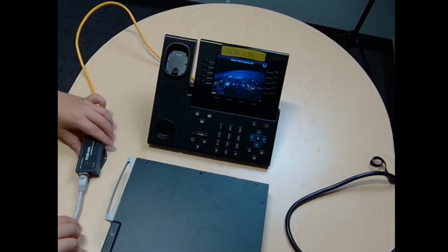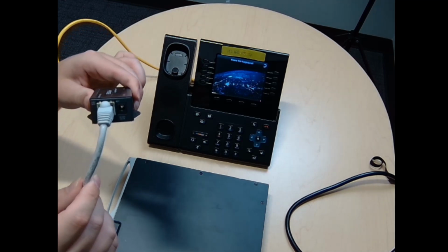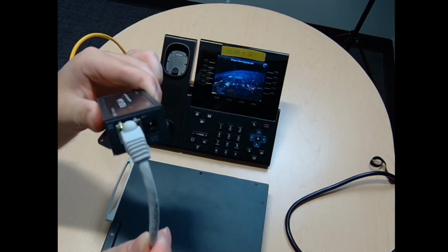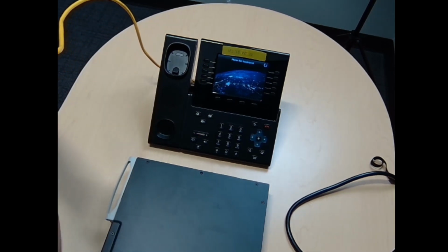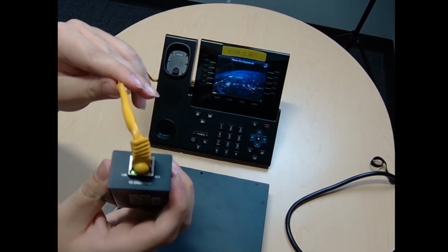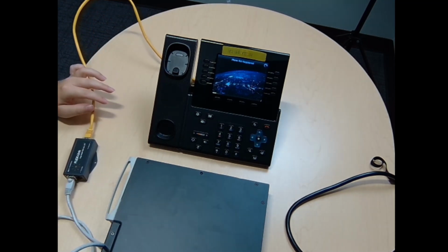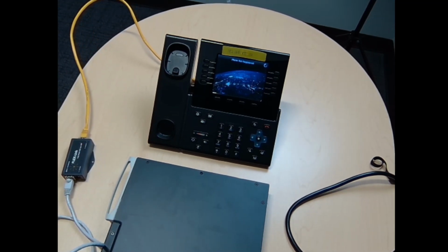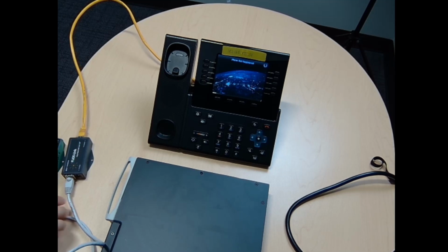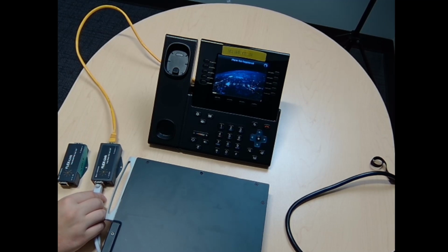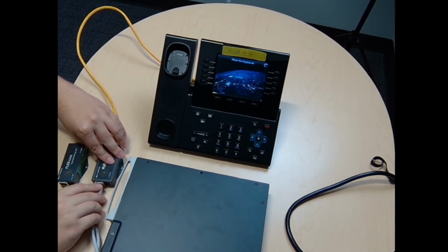If the issue persists at this point, then it is likely that there is a fault with either the end device or with the adapters connected to the cabling. From here, we can examine the adapters to check the LEDs that are present on the devices. It is important to note that devices that are powered by either local power or through PoE will have active LEDs indicating power and data. If none of these LEDs are present, then we can assume the device is not being powered.